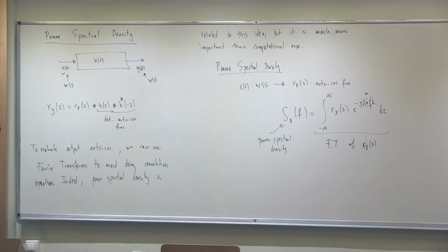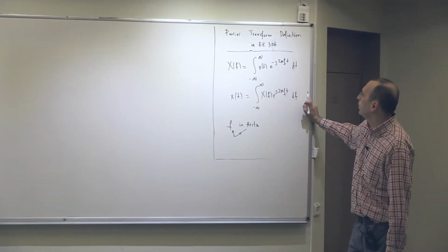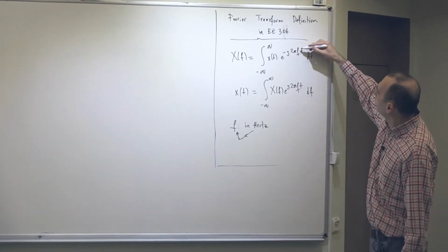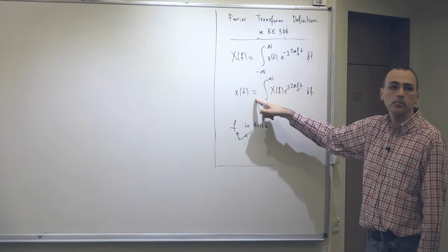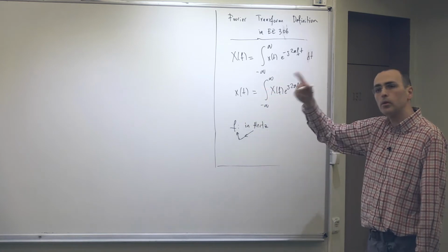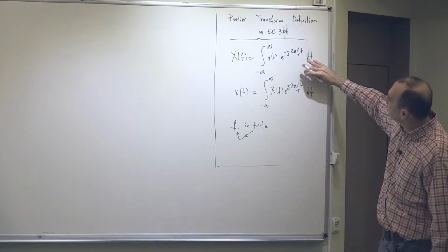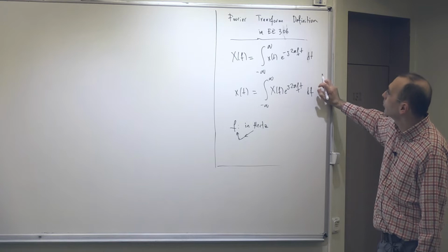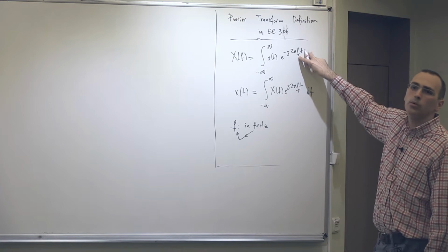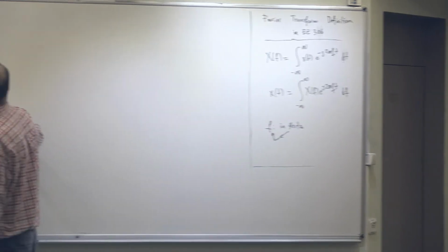Actually, this is a much easier definition. Why is it an easier definition? Because the inverse Fourier transform becomes almost like the forward Fourier transform. The only difference is this plus minus change in the exponent. If I use omega over here, maybe you can remember there is a 1 over 2 pi factor in the inverse Fourier transform. Okay, that was causing some difficulties in the sense that in the duality application and so on, there are 2 pi factors coming up, isn't it? There are things like that. But this one is a symmetric definition. It's very convenient, and this is the definition that we use because it's a practical course. In this practical course, we will be thinking about frequencies in hertz. Okay. Of course, all Fourier transforms are the same. Whatever you call it, it is the same Fourier transform.